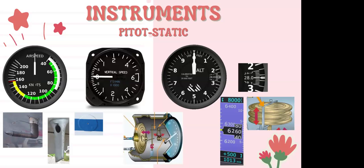Does anybody know, if you were listening to the weather, what would the altimeter setting be on a standard day? 29.92. That's correct, 29.92. So inside of that wafer, we essentially have sealed 29.92, which is a standard day at sea level.